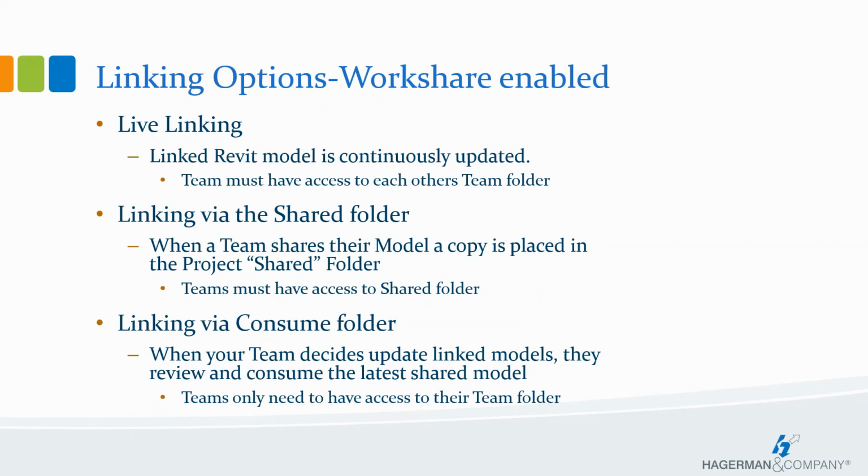So there are three workflow options when linking Revit files to BIM 360 models. So we've got the live linking, which is your basic linking option, and is similar to multiple teams linking to each other's workshared models on a local server. With live linking, teams link workshared Revit models from BIM 360 directly to their Revit hosted model.